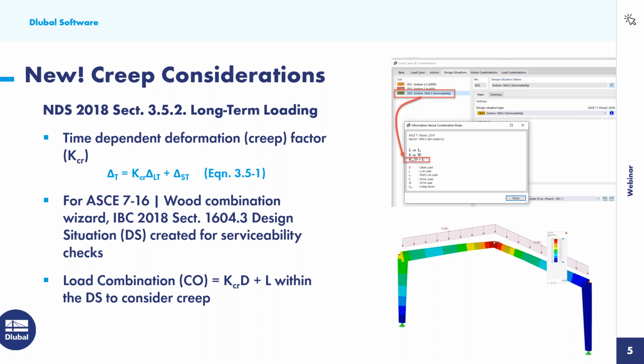And within these load combinations designated within this design situation, one of them will include this creep factor multiplied by our dead load. That's in order to consider creep.